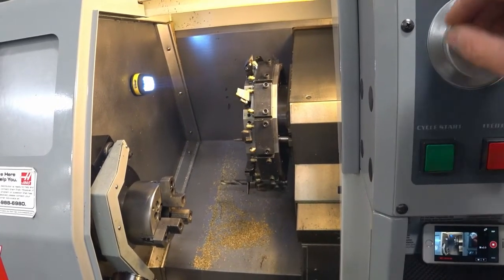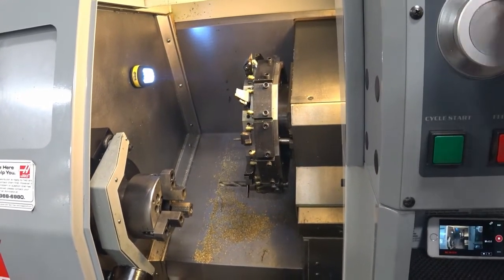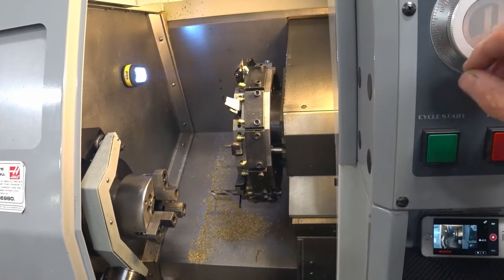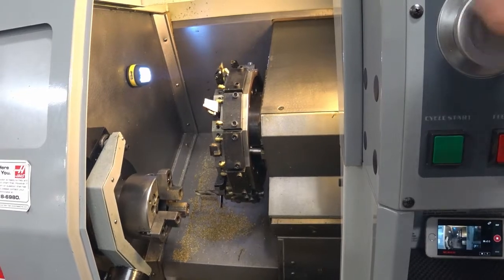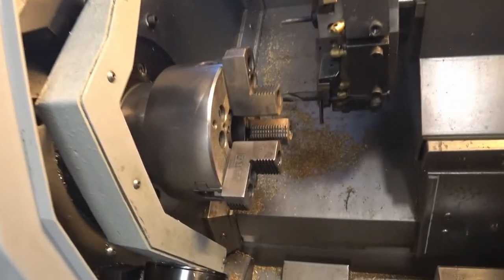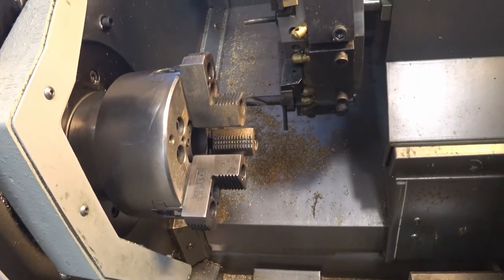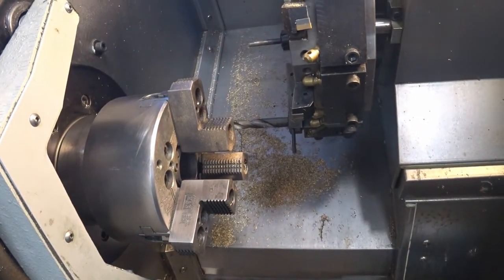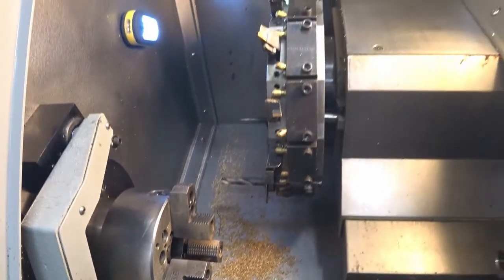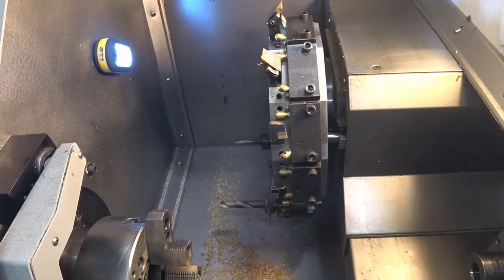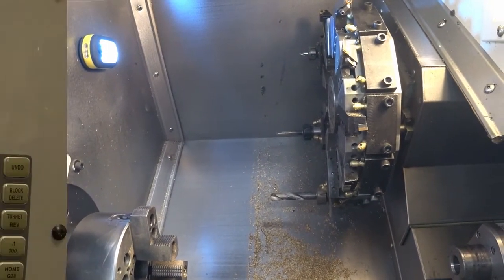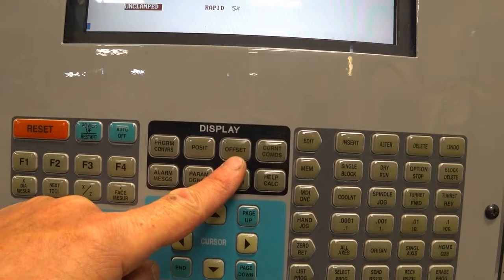Note the proximity of the long tools previously mentioned at the back of the carousel. These tools are loaded in the carousel but are not currently being used. The operator must be aware that this particular situation could result in damage to both the machine and the tools should either come into forced contact. Careful planning of machining operations is required to ensure this does not happen. The control only knows the position of the active tool. Neither tool in the background is active, and therefore its position is only known by visual confirmation by the operator.